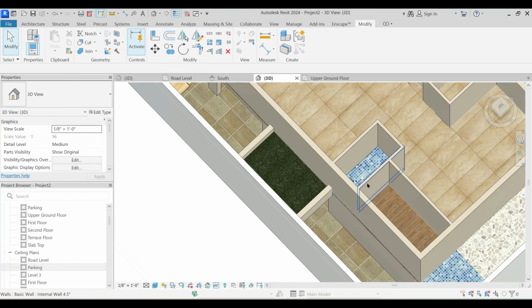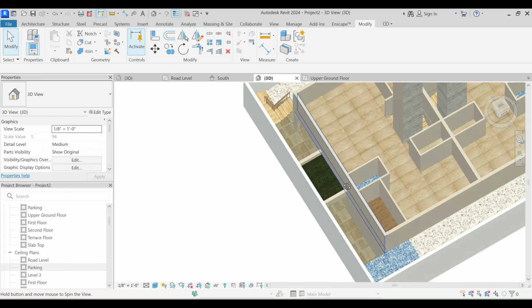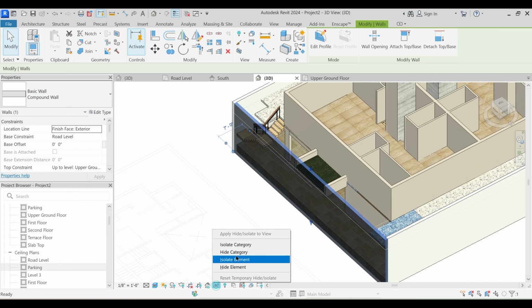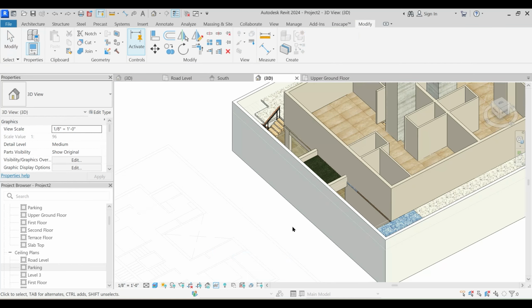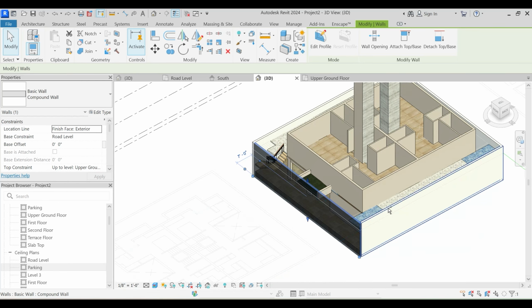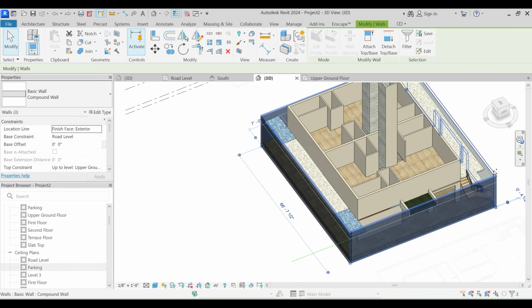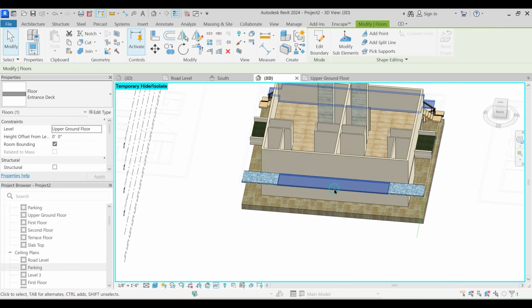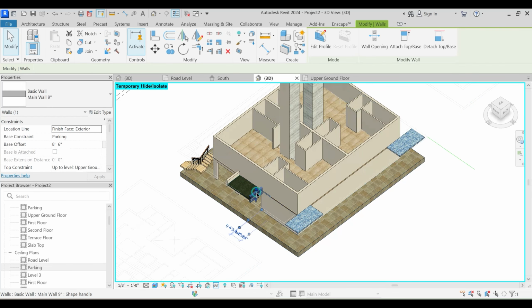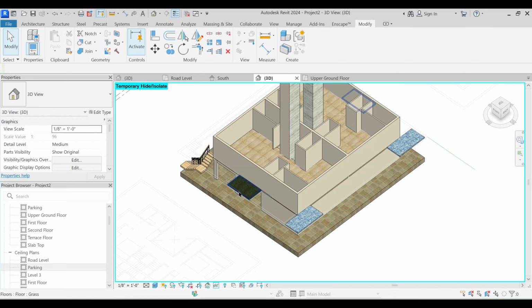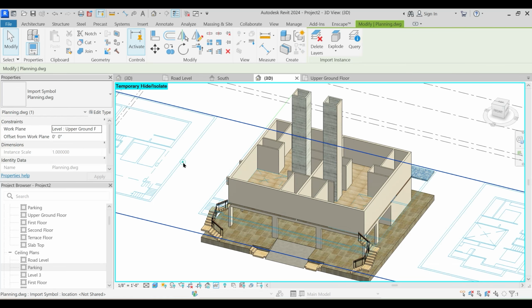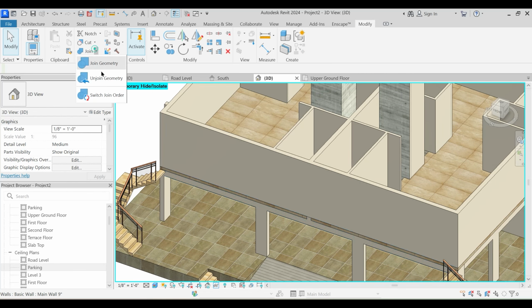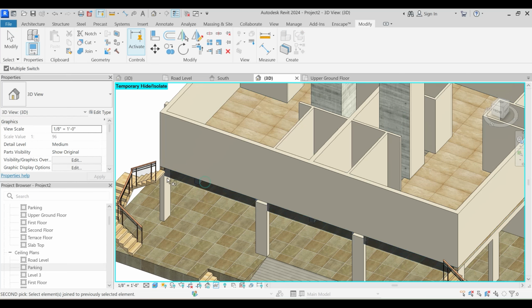And I guess that okay, accidentally I happened to, so just select this and say that hide category. Okay, but that will hide all the walls, so you have to manually do it. Anyways, not an issue. I'll just select these 4 compound walls and this entire floor plate. Okay, and H, and fine. And also let's hide the AutoCAD plan. Okay, now what you need to do is that this particular thing is joined. So you just need to switch order in order to properly visualize this thing.